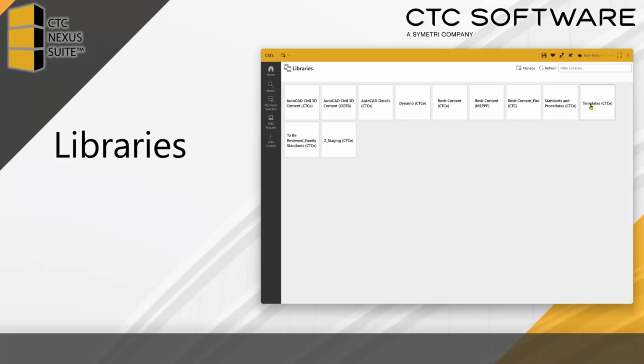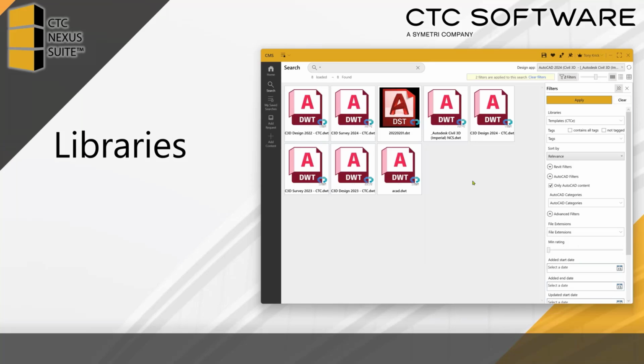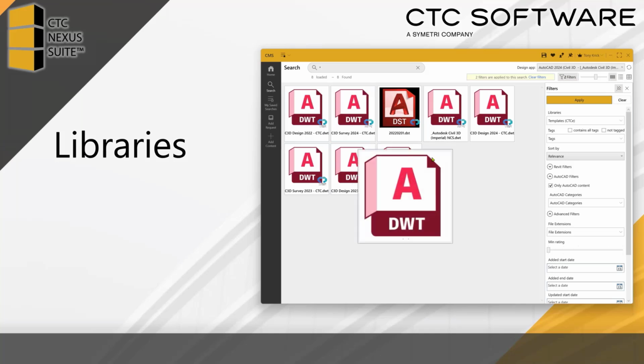First I'm just going to show you this right here because I think this is a handy thing to have. If I hit my template drawings and come over here, and we're going to do this a lot today, and I say only AutoCAD specific, now I get a list, even a sheet set style, over here too. And then I can see all of the drawing templates that have been made available to me to start off with. If I wanted to start a new drawing, I would just simply click this and away I go. All you really need to know is the name of whatever you're using if you're doing a design, a survey, that type of thing.